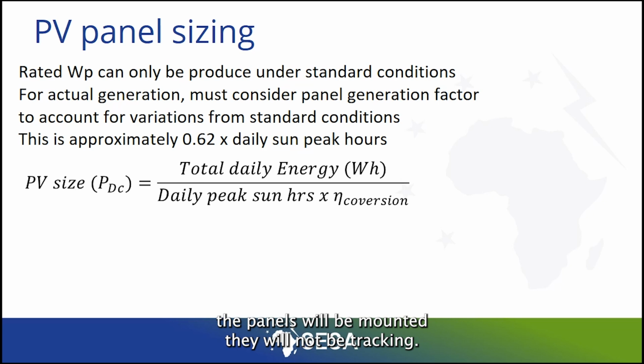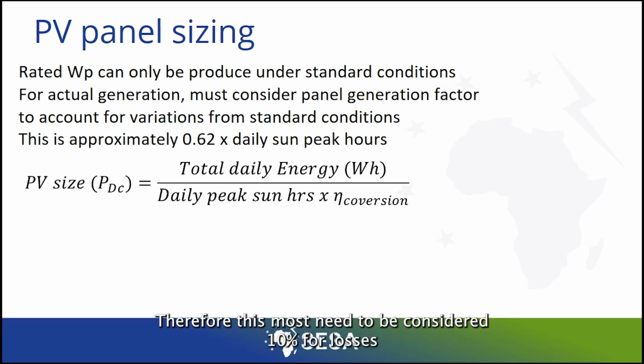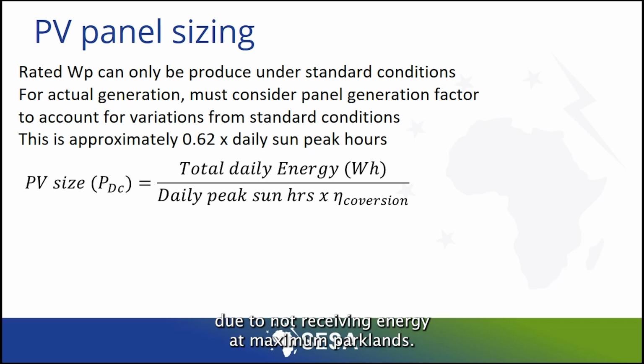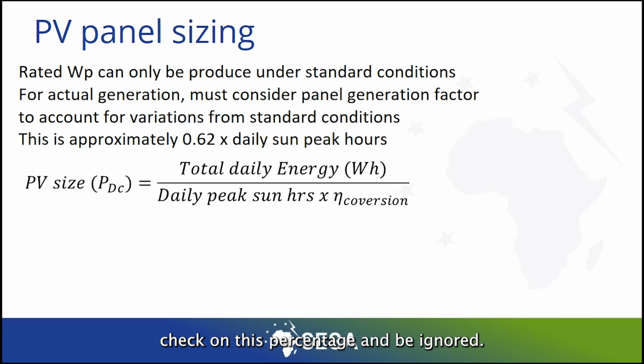They will not be tracking. Therefore, this loss needs to be considered: 10% for losses due to not receiving energy at maximum power point. However, when the charge controller is a maximum power point tracker, this percentage can be ignored.